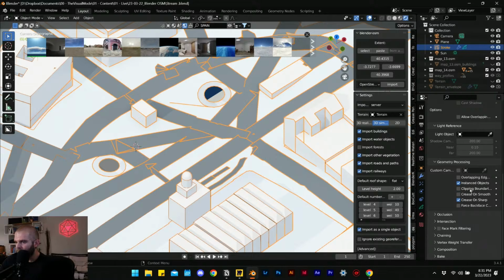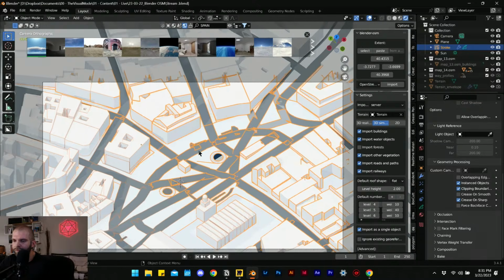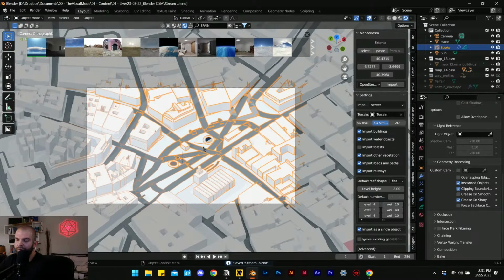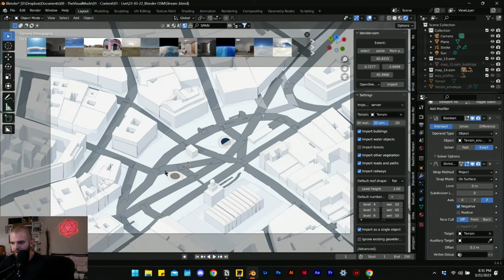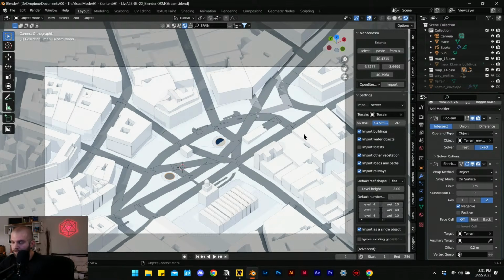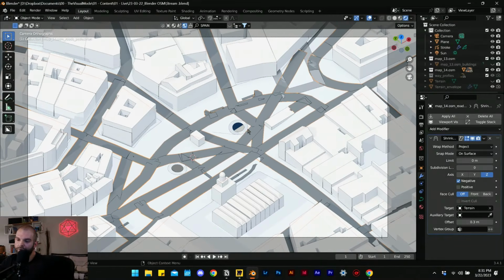I do have it as a point to, at one point, have this finessed enough. I think this is a relatively new feature that they've added in, this modifier for line art, although they've made a few tweaks to it in the late updates. So hopefully they keep updating this and we can have a bit more control over the line work and be able to add different thicknesses. I mean, the way to add different thicknesses would just be to add different lines, but this is as max line thickness as we're getting at this moment.